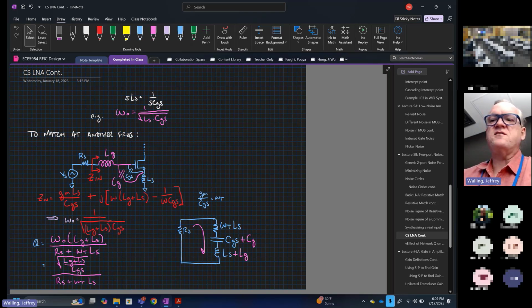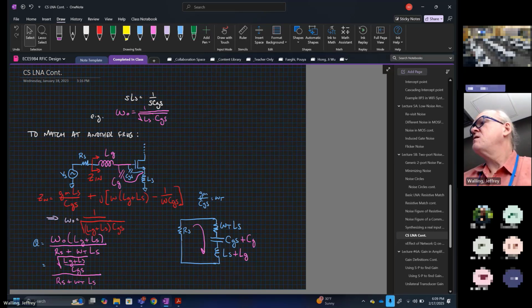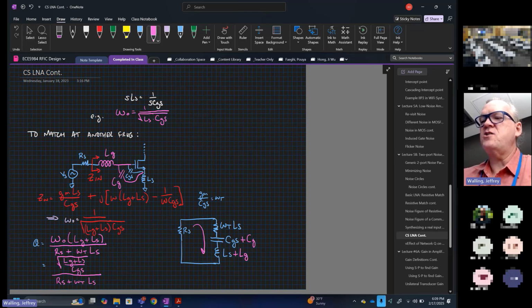And while it's true that to the outside observer, the impedance of the inductor is exactly equal to the negative of the impedance that the capacitor presents, so there's no net reactance at the resonant frequency, the reality is that you're trading energy back and forth between the inductive element and the capacitive element.